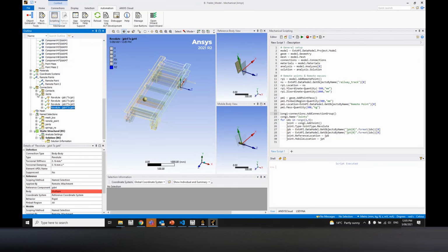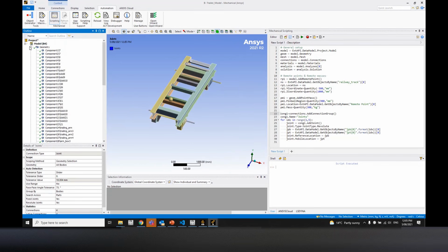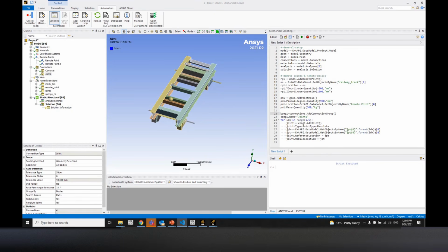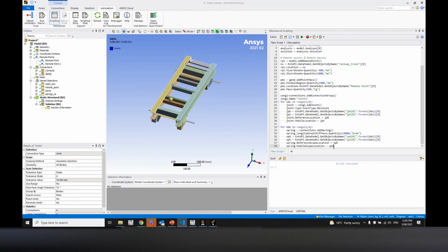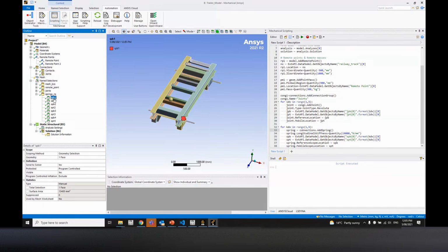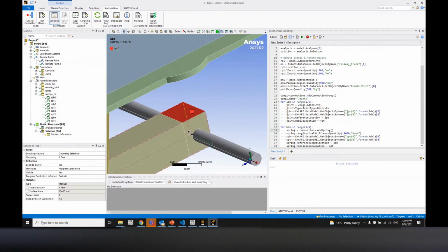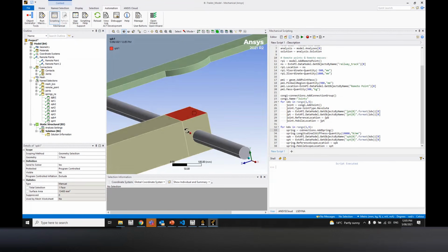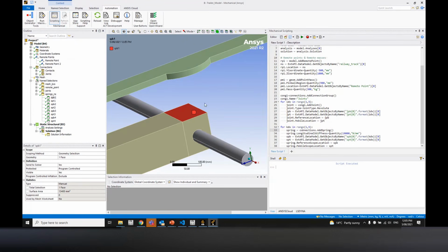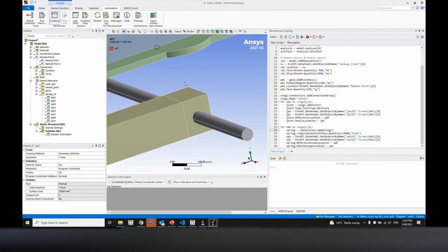Okay. Cool. So what I then do is I do the same thing for Springs. Same concept. I'm going to copy paste the script here. I'm not even going to record it this time around because we've gone through this. Sorry, and I'm going to paste it there. Same concept here. If I go to my Spring NS, I've set up my Spring NS. Instead of JP, I've just changed it to SPB. SP being Spring, B is bottom, P is top. That's it. So this is SPB1, and then SPT1 would be the top surface.